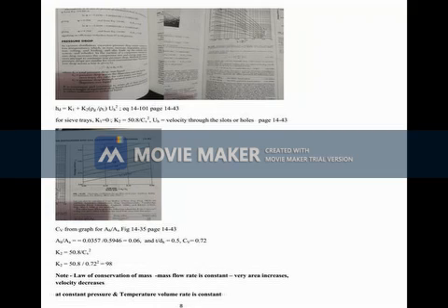So find out the slope. The operating line slope is LS by GS. Then you straight away construct the operating line and construct the triangle.